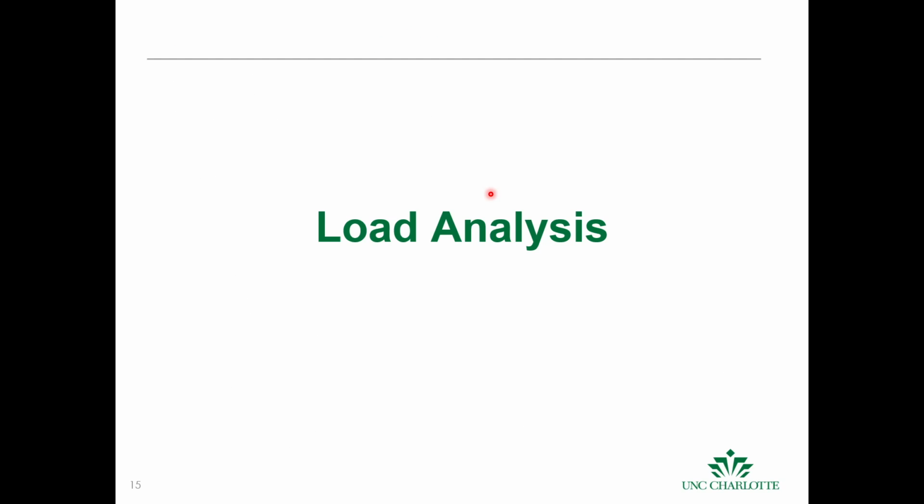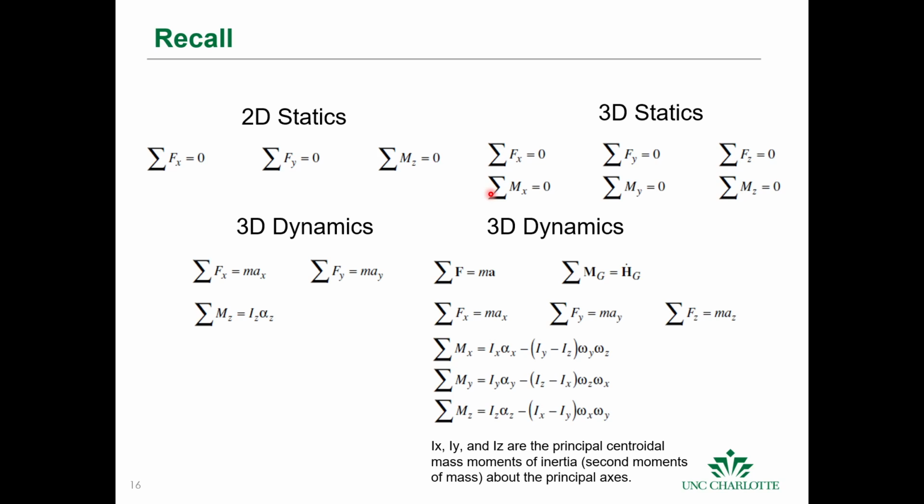All right. So the rest of this lecture, we're going to go through the load analysis, and we're going to go through an example. Okay. I'm going to summarize 2 entire courses that you took. Statics, the sum of forces and the sum of moments is 0. In the 2D case, we usually use sum of forces in x and y are 0. Sum of moments are 0. 3D statics, the sum of forces in all 3 directions, if we were using Cartesian coordinates, is 0. And the sum of moments about x, about y, and about z are also 0. So that's pretty much the main equations that we learned in statics.